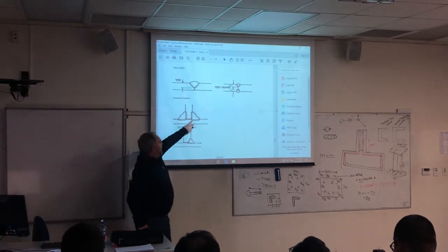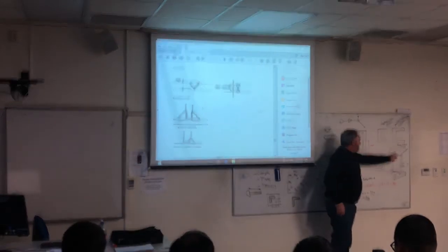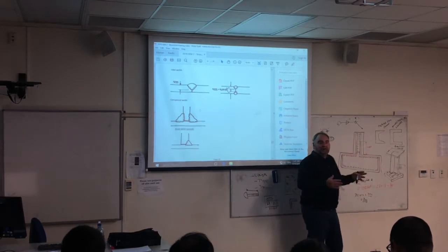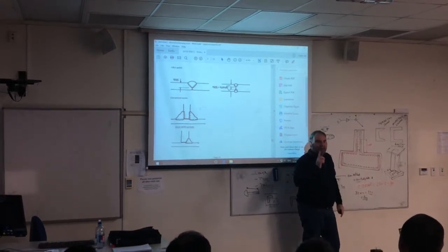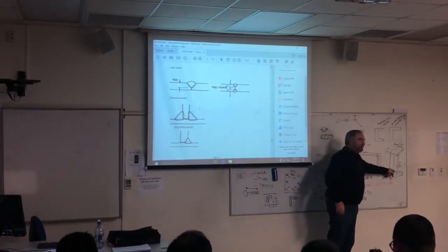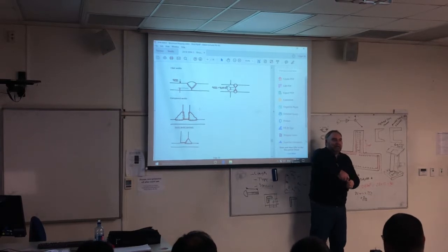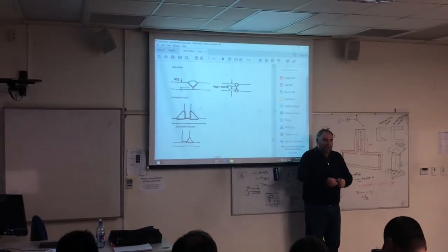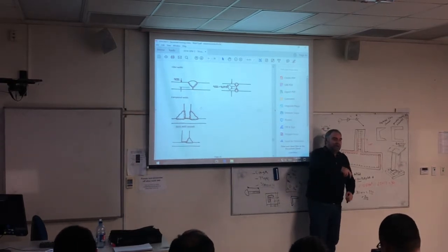When you're putting your holes in this plate over here, remember the angle doesn't go through the plate, so you don't have to use the angle as a minimum or maximum. But you don't want to put the holes too close to it, because you won't get a crescent in there to tighten up the nut. And I think older students here will know exactly what I'm talking about. Well, if it's not a crescent, it could be a socket.